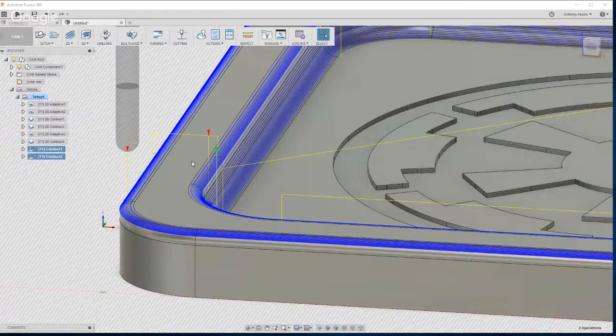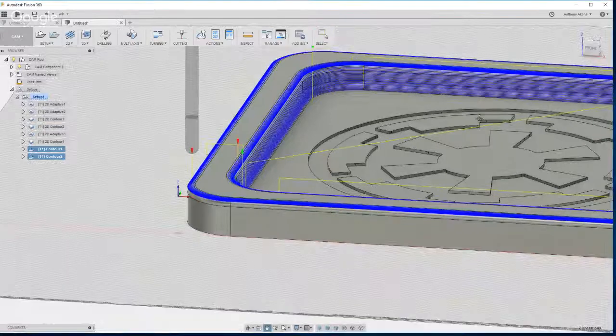You can do a tool change, but it's much cleaner to just do 2 runs, because then you can reset your Z-axis, change your end mill, reset your Z. Don't zero your XY, just your Z. Touch it back off to the top of the stock, and then just start the second job from there, and it should run and clean it up.